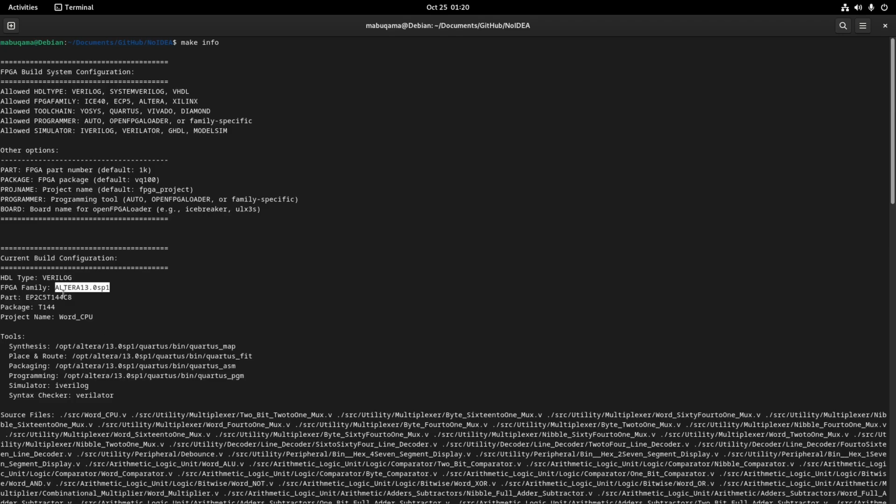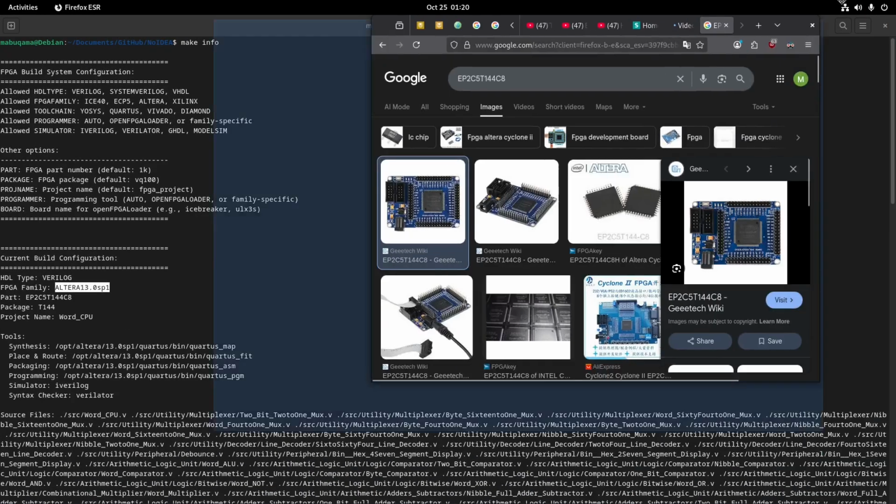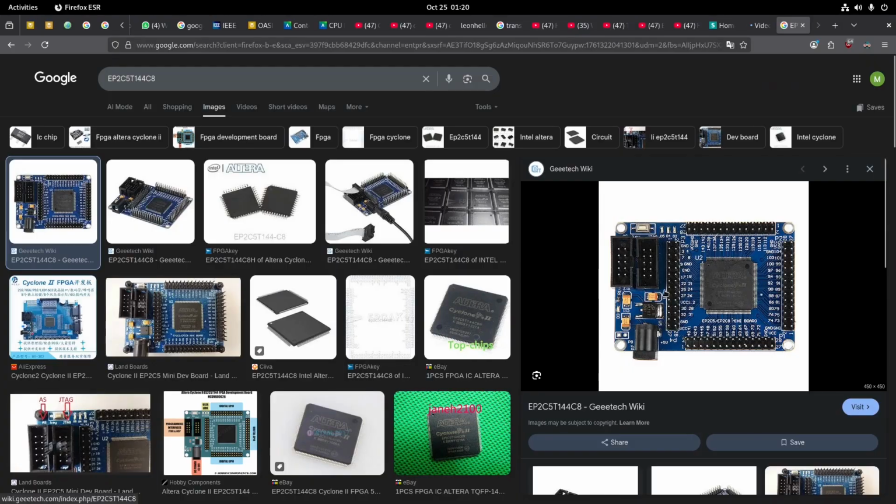It's the EP2C5, which looks like this. I'll bring it in. All right. So basically, this is my power port. My left and right are JTAG connectors. These are what's being used to actually program the FPGA. The one on the right is a temporary program, so it's volatile. It doesn't actually save to the chip, and the left one does.